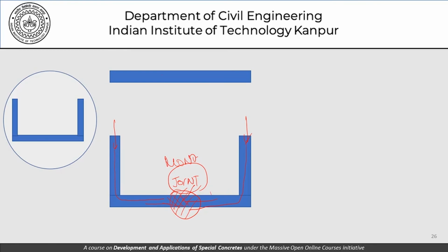Apart from that, we also need to ensure that we have formwork on the top, because after this concrete has been placed, this part has been filled up, we will expect the concrete to rise as far as these walls is concerned. So this will happen only when we have the top surface here having the formwork.